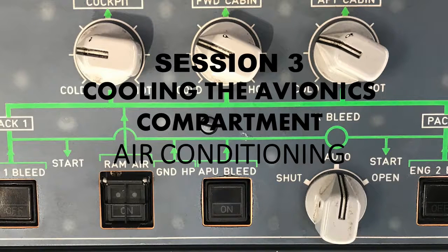There are different push buttons that we're going to be involved with here. There's the override, OVRD: override blower, override extract, and then one for both. Pushing any of those buttons is going to close the skin exchanger inlet bypass valve. Remember I said earlier what opens? The outlet bypass valve. I don't want you to get confused, I'm just trying to make it clear that we're talking about a skin air inlet and a skin air outlet.